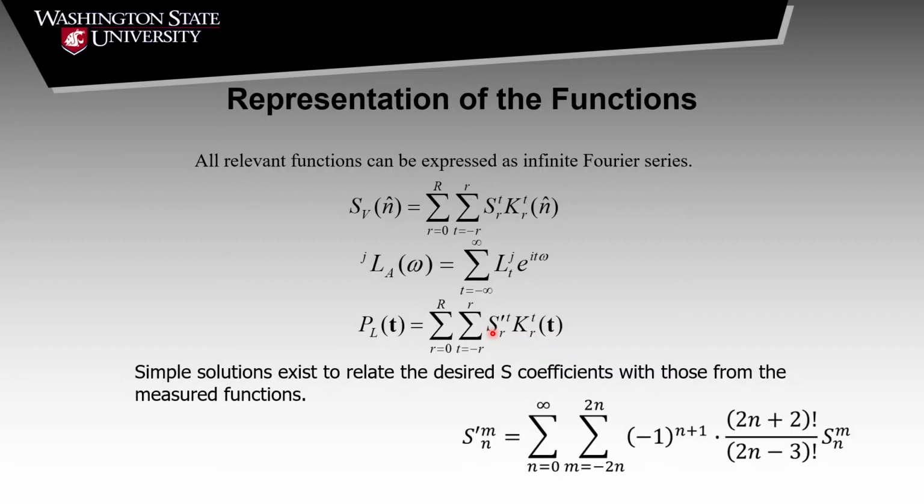So each individual measurement you take, you calculate these directly. So you know this function. This is the function I'm scanning in this direction t. I have this many intercepts per unit volume, right? So I can do that directly. And then this known function I can represent in a Fourier series expansion over the same space. Right now it's not a scan direction that I'm representing, it's the boundary normal orientation.